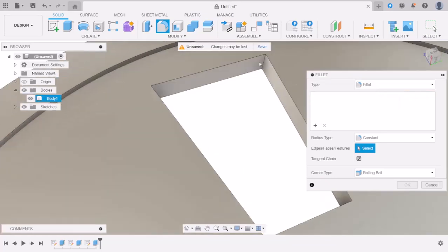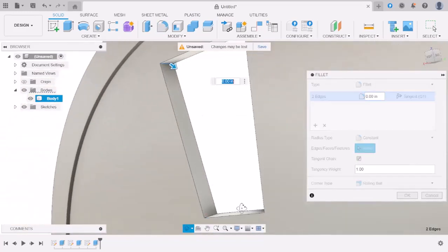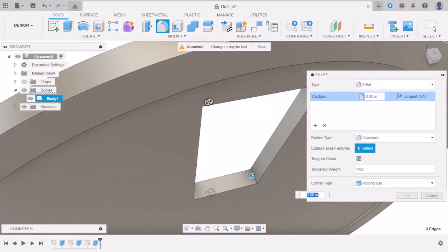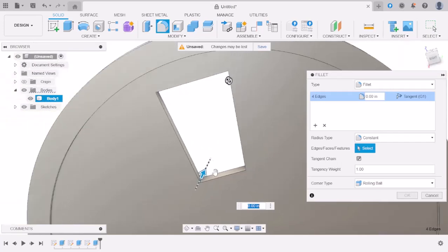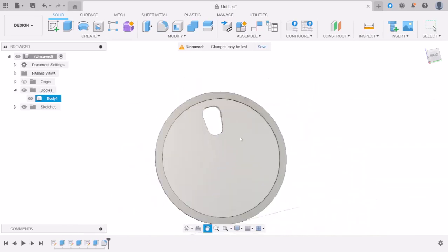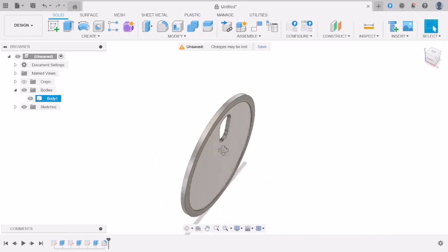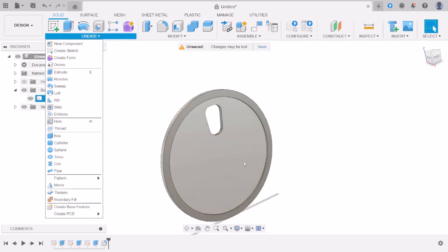So we can select most of this angle where I want to fillet, and here, and let me move out. Okay, let's fillet this to, let's see, 40 is fine for me, so I'll click on OK. Now this is done. You can see it's not looking all that nice, but we are getting somewhere. Now what we'll do is mirror this feature we have here. I want to pattern it around because I need 4 of it, not 1.